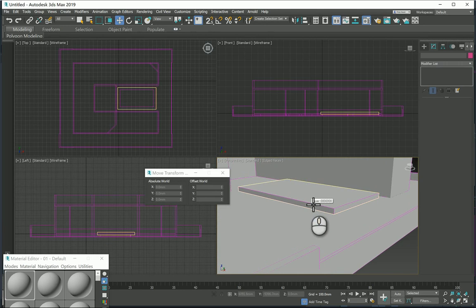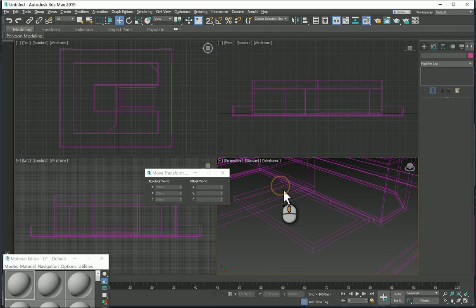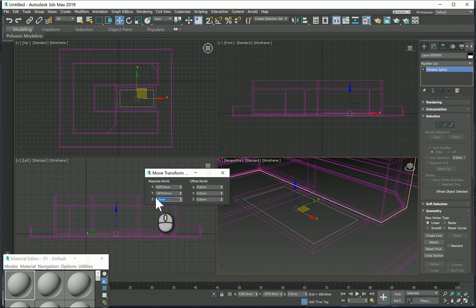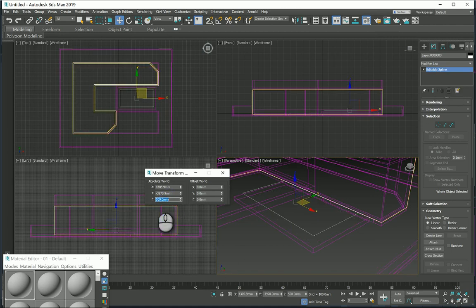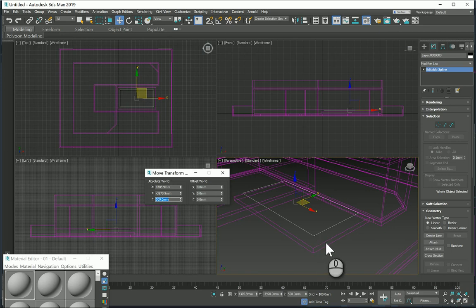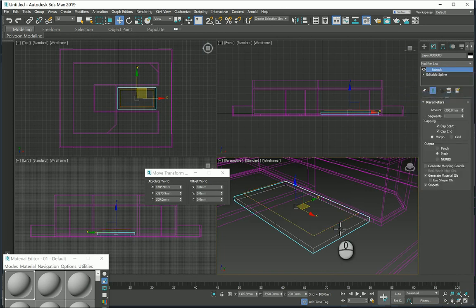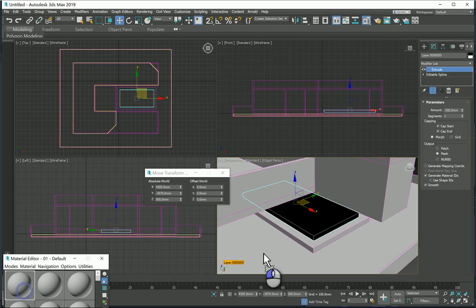So hit F3, in my case function and F3. I need to change the view location. Be careful when you select it. Here you should see no extrusion, so that's a pure 2D spline, and I'm going to place that as promised in the Z value of 500, and then maybe it's the time to steal this extrusion, which is minus 300, because it is the same. So paste, hit function and F3, or just F3, depending on what type of laptop you have. And here we go.